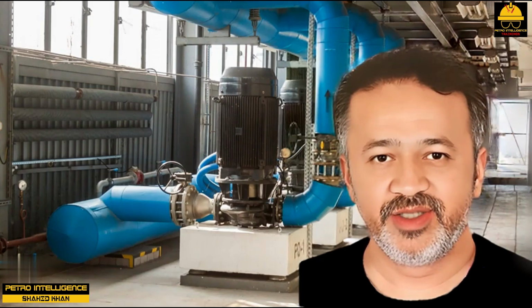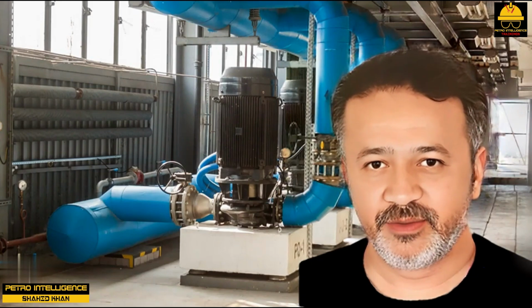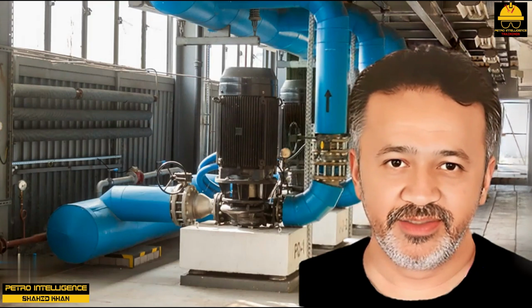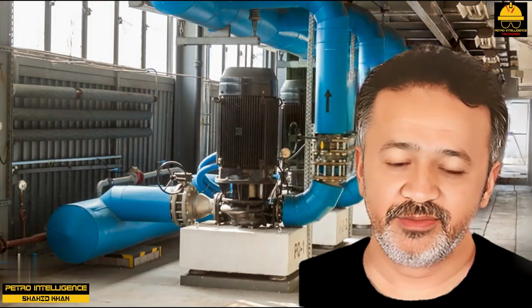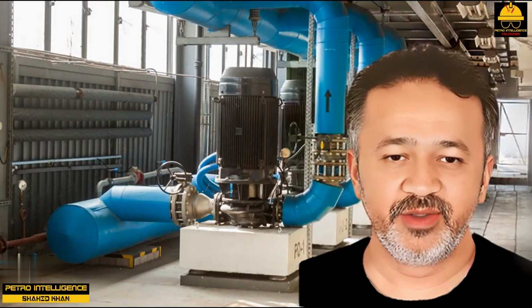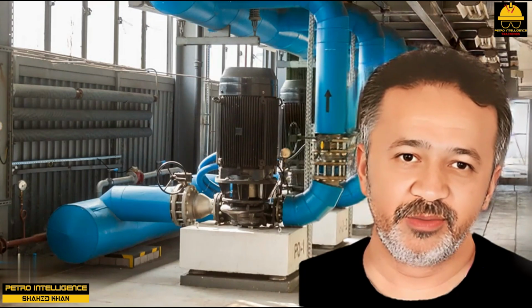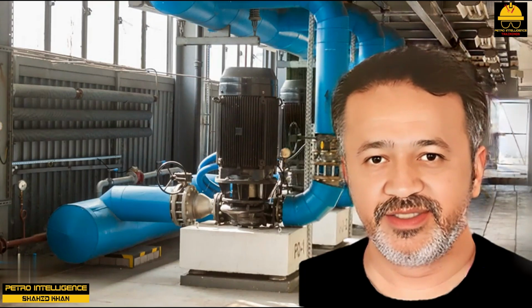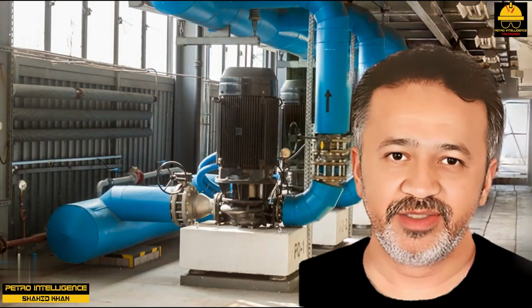This happens because of a disturbance to the liquid as the vanes spin past the volute or diffuser, that is, the case outlet opening. Exxon had at one time a standard of keeping impeller sizes at not more than 92% of the full impeller diameter. This seems a conservative practice to me.